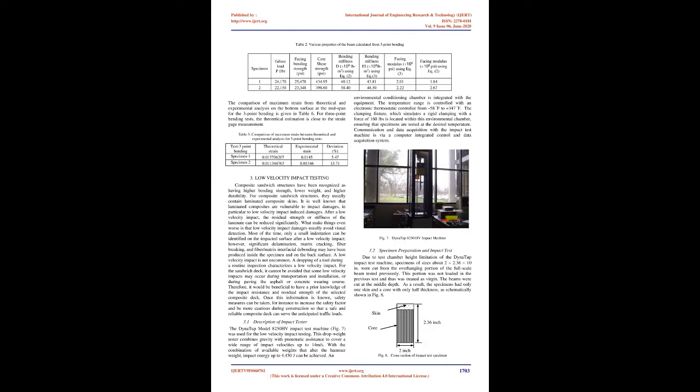For measuring the deflection at the midspan of the beam, a LVDT, displacement transducer, is attached at bottom, 3-point bending, and top, 4-point bending, of the midspan of the beam and supported by the load plate of the machine. The LVDT is attached with a data acquisition unit, Cooper Data Chart 2000, which gives the instantaneous displacement of the beam. To determine local strain, the strain gauges are mounted at the top face, the side face, and the bottom face at the midspan of each beam. A Yokogawa unit is used to measure the local